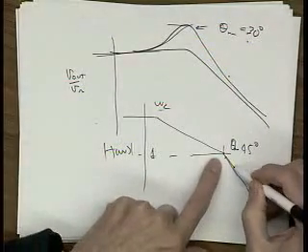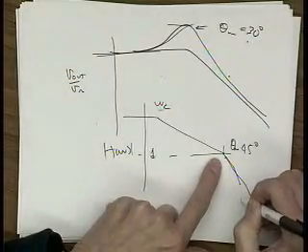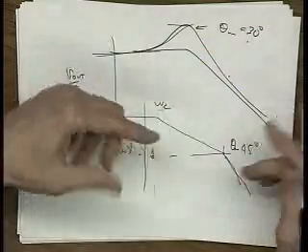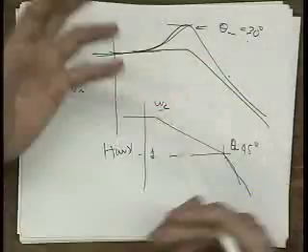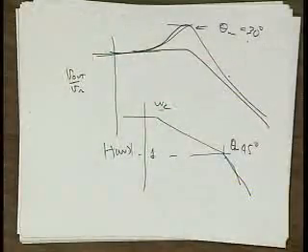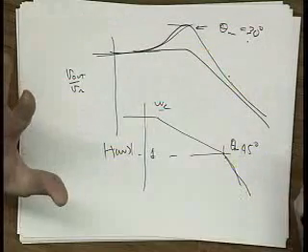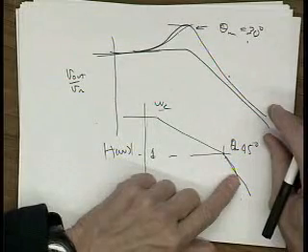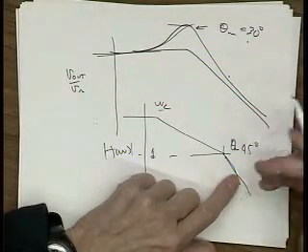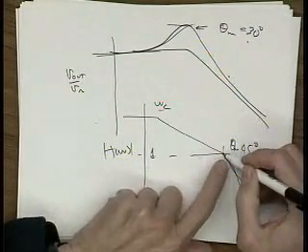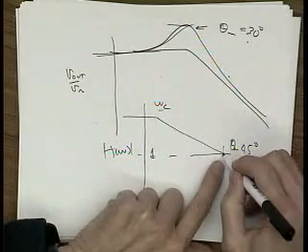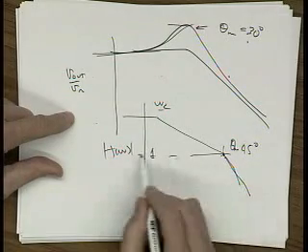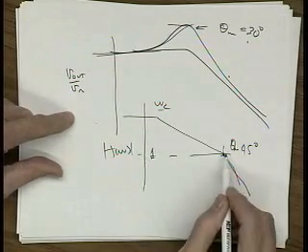There's a lot of other poles going on here, right? And I showed you what happens when you put a circuit in feedback that has multiple poles and zeros: the poles and zeros just move all over the place. Fortunately for us, because we don't want to figure out that problem. That's a really tough problem to figure out. Spice can do it, but by us just looking at what's happening at this first pole where the unity gain frequency is, at that point right there.